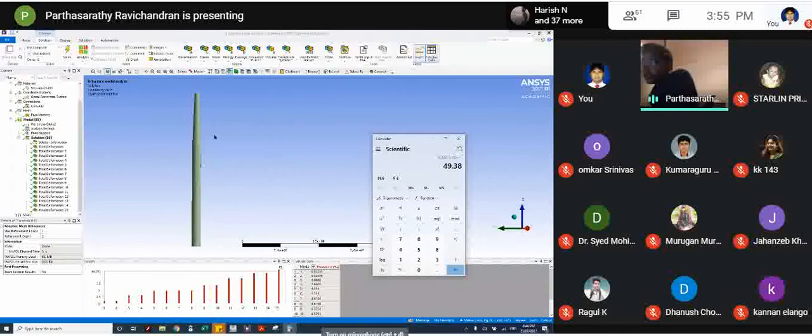Let's say there is a turbine that has been designed where we are seeing 49 RPM close to that, then we would try to improve the tower's thickness or stiffness of the whole structure and keep it away from this RPM. The other option is, if this RPM cannot be avoided, then you have only the control systems as your major function to increase or decrease the RPM whenever it is coming close to the natural frequency of the tower.